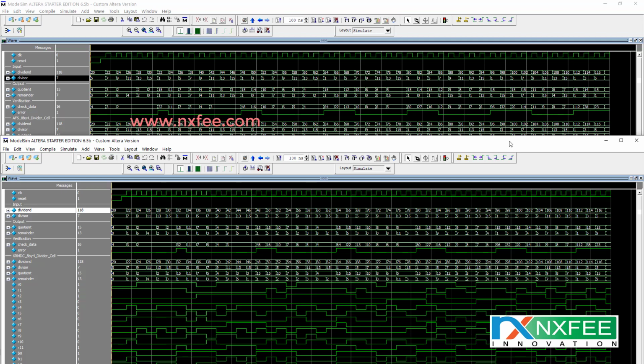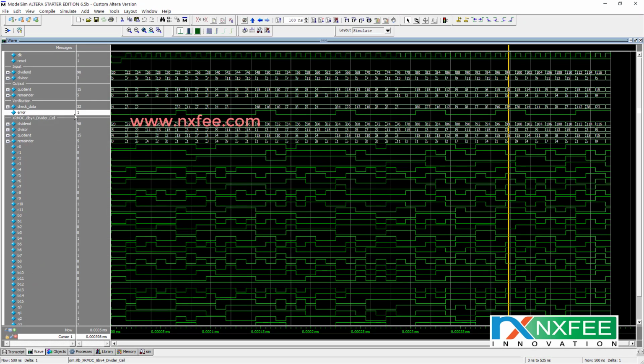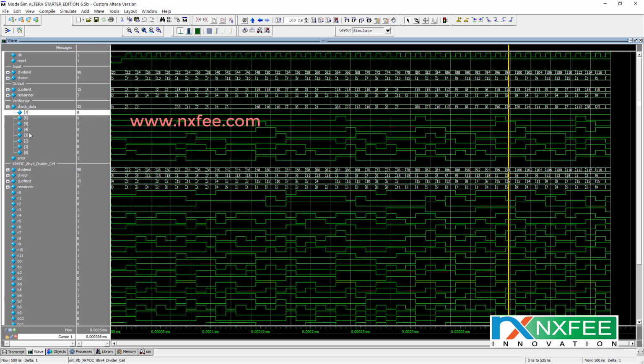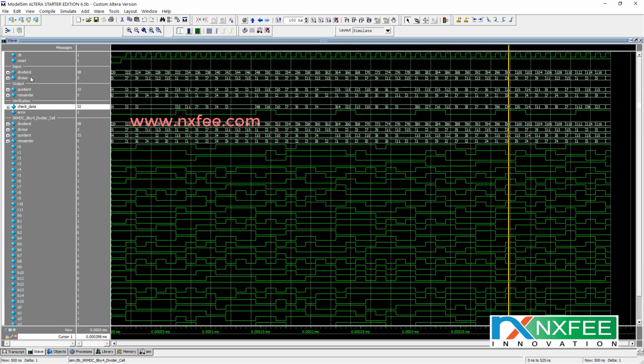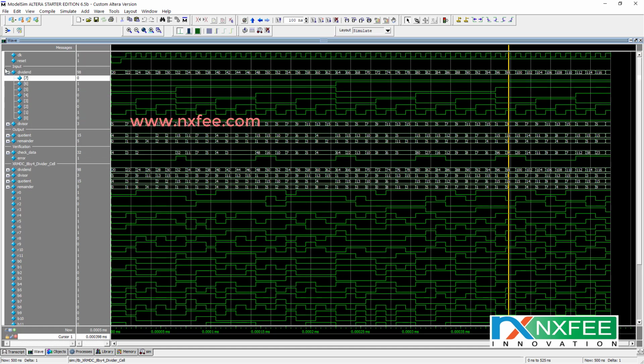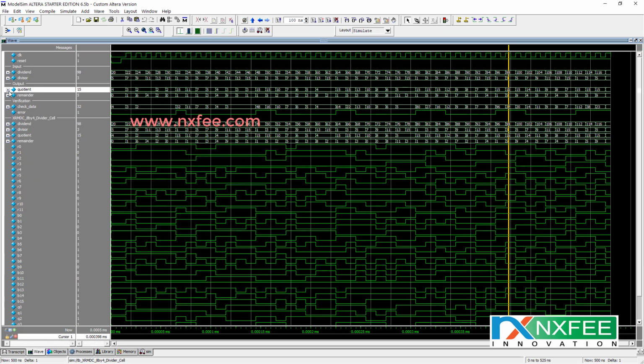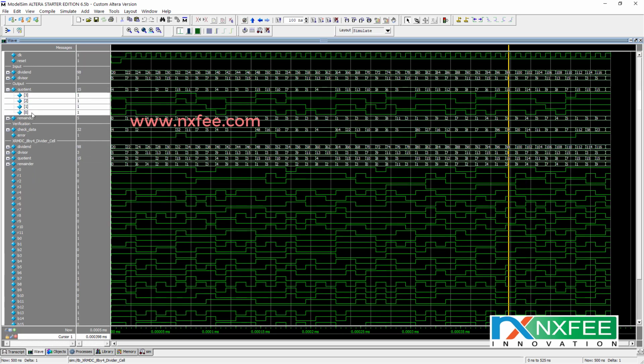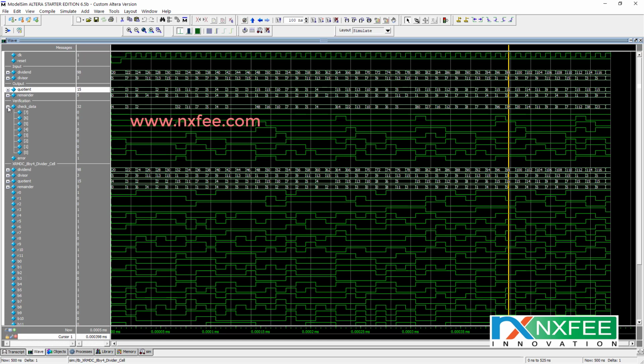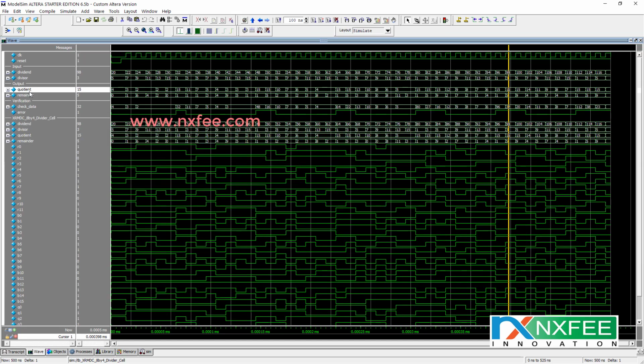Okay, but in some cases the error will be produced in the exact method. Why? Because we are checking the check data equal to 7 down to 0, and the dividend equal to 7 down to 0, but the divisor equal to 3 down to 0. So as per the architecture we have taken the quotient equal to 3 down to 0 only, not 7 down to 0. So it will be truncated, and the truncated balance output is only produced in the output of quotient and remainder.